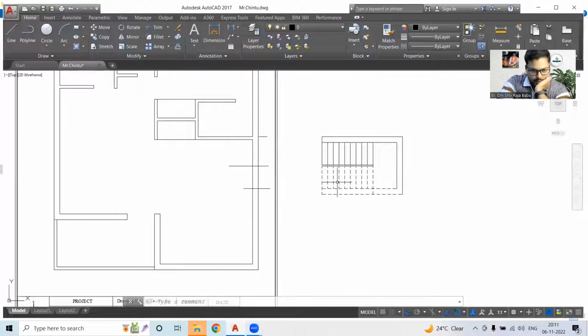So there are 2 ways of doing that. Either I can change the staircase height over here. Okay. So I will have to add a few steps on this side, but those few steps will be too much over there. Okay. So I will have to just increase the height by 2 feet. So at least I need 1, 2, 3, and 4 steps on this side. Okay. So I will have to reduce 3 steps from here. I will have to increase 1 step over here. Okay. So the building height will be raised, and then we can have 21 steps so that it can be 21 feet 6 inches. Okay.